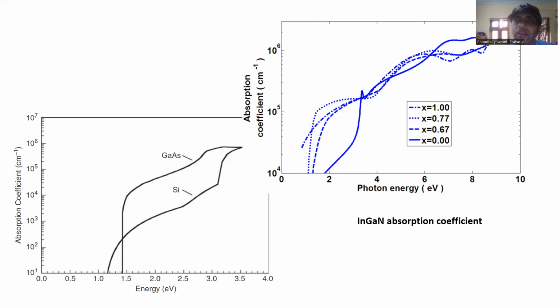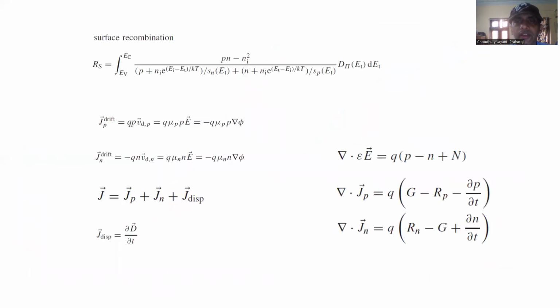And the effective mass determines density of states. Now, what this means is that at a specific equilibrium or quasi-equilibrium, there are more heavy holes and fewer split-off holes. And since these heavy holes have large effective masses, that decreases the transmission probability and makes it difficult to obtain good ohmic contacts with these devices. And so those are things that need to be kept in mind in order to optimize solar cell device performance.